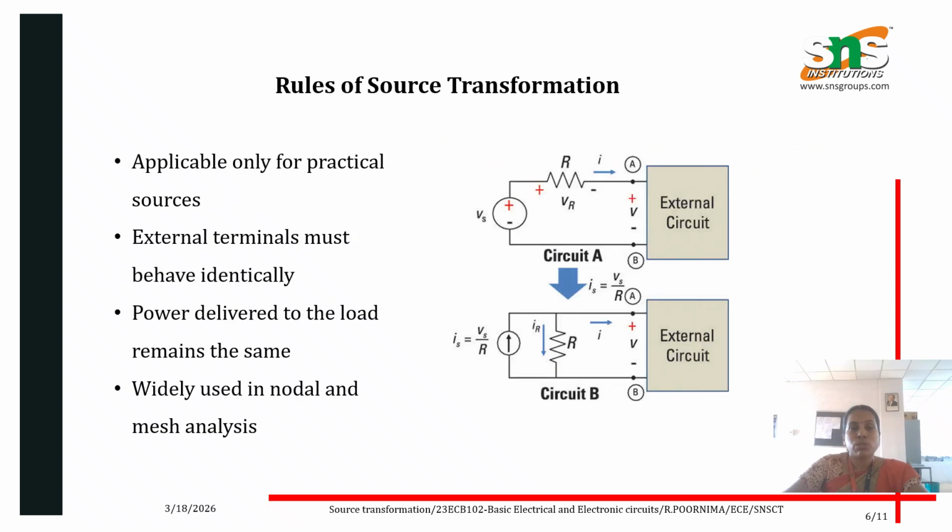And the rules for source transformation. This method is applicable only for practical sources. The external terminals and external circuit must behave identically. Power delivered to the load remains the same. And also it is used in nodal and mesh analysis.